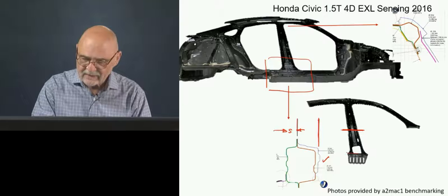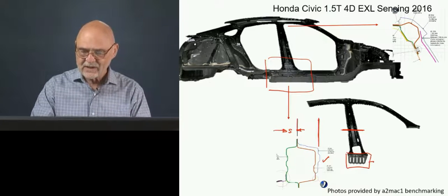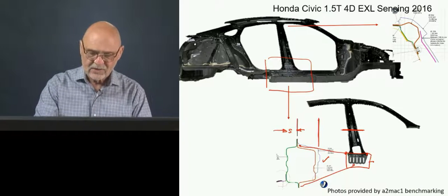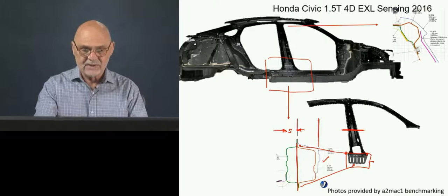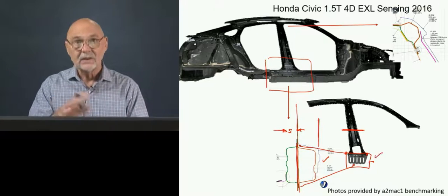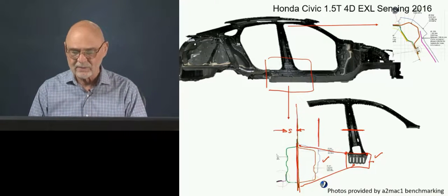But you see this kind of thing that looks like fingers coming out here. This actually extends down. This point here is at the flange. So it's actually continuing this down so that internal to the rocker there is this continuous shear wall. Okay, so again, very, very good applications of some of the principles that we talked about.